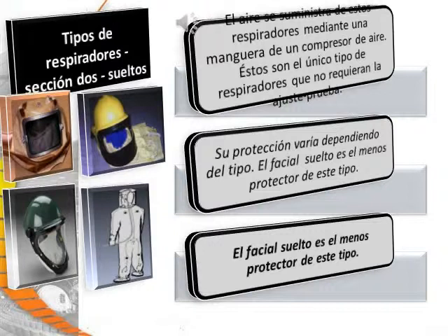Loose-fitting facepieces are the least protective of the types of supplied air respirators. Air is supplied to these respirators by means of a hose from an air compressor. These are the only type of respirators that do not require fit testing.